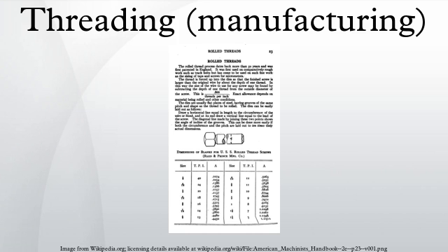Note that solid multiple form thread cutting tools look similar to taps, but they differ in that the cutting tool does not have a back taper and there is not a lead and chamfer. This lack of a lead and chamfer allows the threads to be formed within one pitch length of the bottom of a blind hole. Thrilling is the process of threading and drilling internal threads using a specialized cutting tool on a CNC mill.